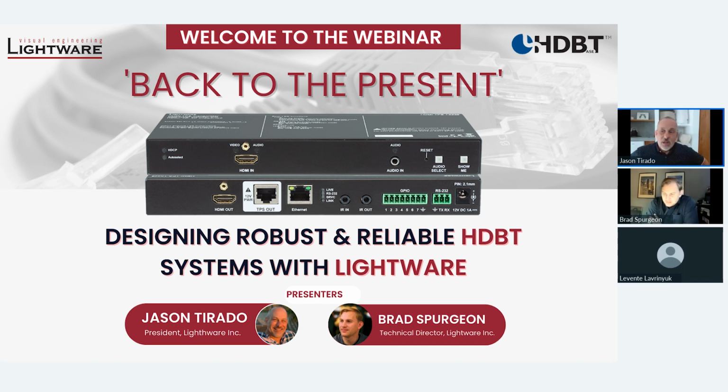In my opinion, as good as AV over IP is, it's not as simple as spelling it. Anybody that's done it knows that there's an immense amount of coordination with the Ethernet switch, the very thing in the very middle. There's all kinds of protocols, IGMP snooping, multicast traffic that may or may not be implemented on a given Ethernet switch. Although there are some great situations for that, it really requires a lot of knowledge about the Ethernet switch and the configuration, and sometimes it's not as easy as just doing HDBaseT.